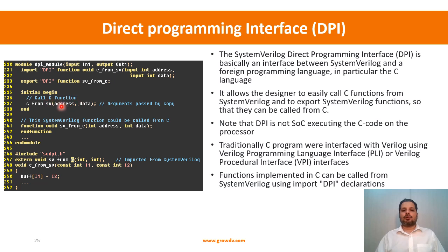When you do this, it will really call the C function, and whatever processing is present over there will happen. It can have return values, and you can get arrays and use those arrays in the SystemVerilog for doing something. So this could be a reference model. You pass some information to the reference model, the reference model does processing and returns some information into the SystemVerilog world, and then you can do some checks or comparisons. That can be your scoreboard.